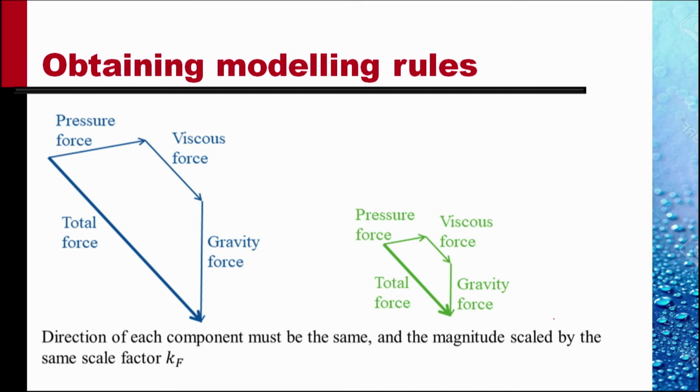So it's not only that the pressure forces have the same scale factor, but the x component of the pressure forces also would have the same scale factor. The y component of pressure forces would have the same scale factor, the direction being the same. Similarly for all forces. This is the basis on which we construct the modeling rules.